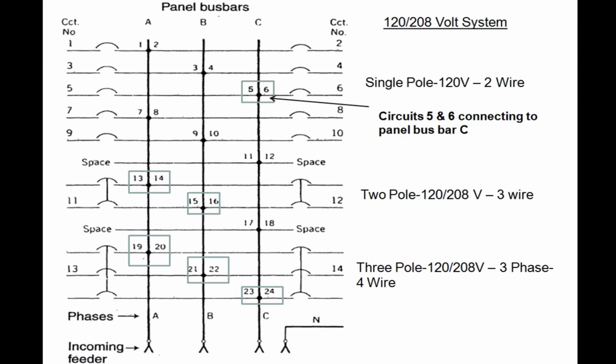Okay, so you see that there's a number of circuits. It's again 3-phase wiring, A, B, and C. The circuits are distributed evenly across those 3 phases. Okay, 1 and 2 on A, 3 and 4 on B, 5 and 6 on C, so on. Okay, and you go on through. It tells you there's a couple of 2-pole and 3-pole circuit breakers there.